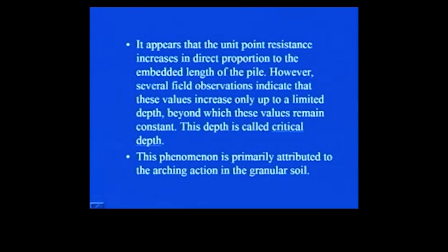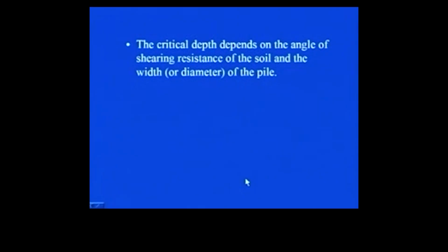This phenomenon is primarily attributed to the arching action in the granular soil. See, here we are talking in terms of driven piles in granular soil. So, you have to be very careful using this critical depth concept. You will use it in the case of granular soil only, because arching action of the soil is present in granular soil only. Now, this critical depth depends on the angle of shearing resistance of the soil and the width or diameter of the pile. Depending on the diameter of the pile and the shear strength parameter of the surrounding soil, this value of critical depth will change from one pile to another.